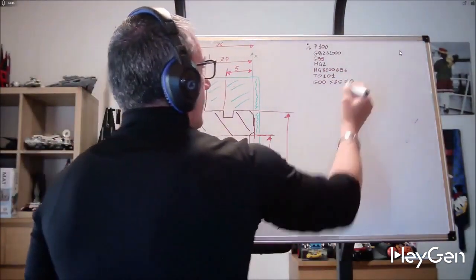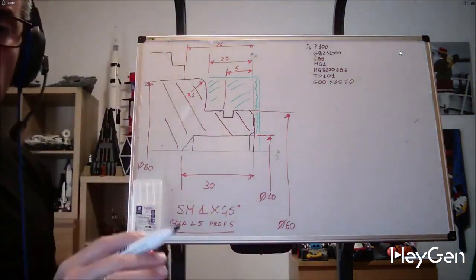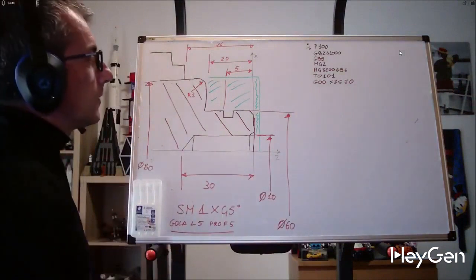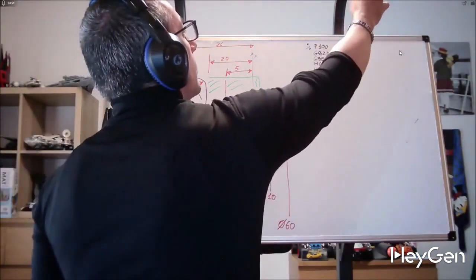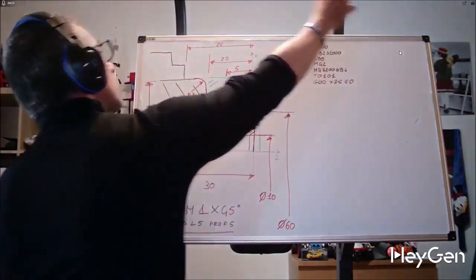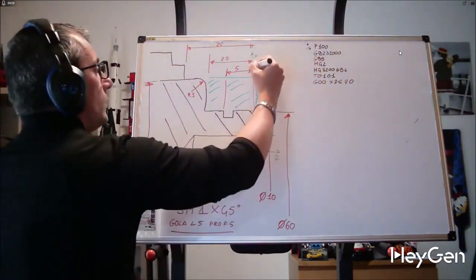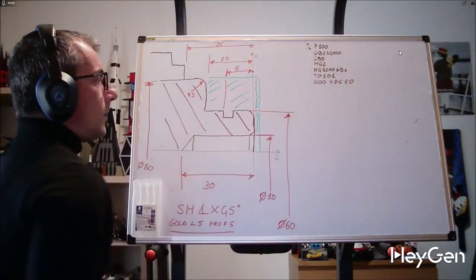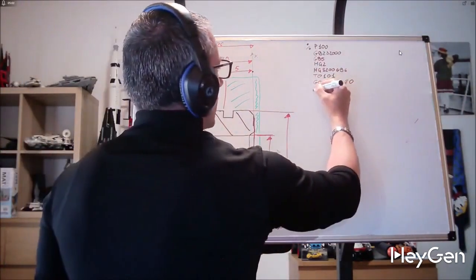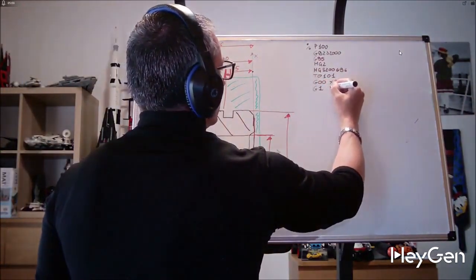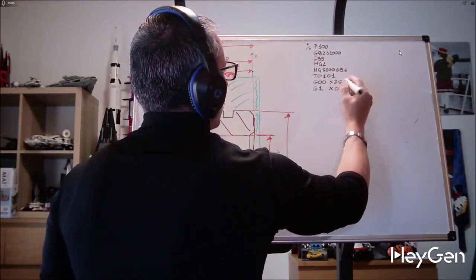Okay, very educational. If I were on a machine, what would I have done first? First, a nice X200, Z300, then first Z0 and then X85. I have brought myself here, perfect. G1, let's do this piece.